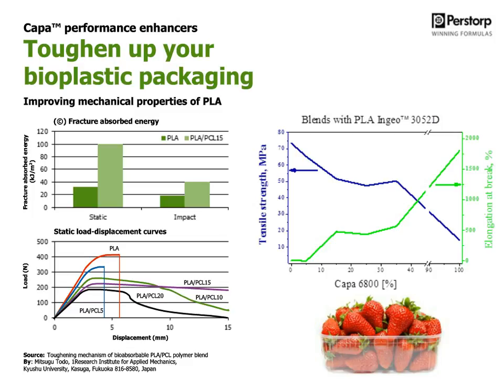And in some cases, 5% is not really balancing this. It's more maintaining the PLA at the starting level. And so you need to go higher, maybe 10 or 15%, to really see an impact of the PCL in the compounding step and in the final results of the PLA. This is something you, of course, can optimize with your process and your skills. And this we have tested and will look into further.